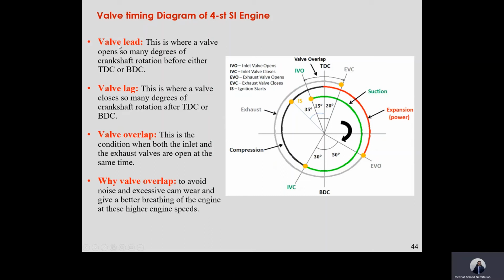And that's why we have some terminology we call valve lead. Valve lead means we open the valve earlier before the top dead center, like the intake valve. Valve lag, we close the valve after the bottom dead center. We close the intake valve after the bottom dead center to allow more charge to come into the system. And we have what's called the valve overlap.